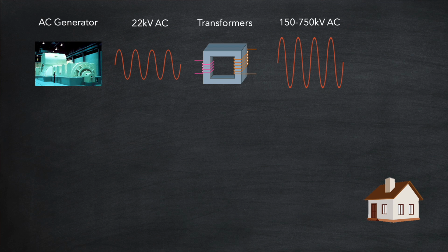They're just two sets of copper wire wound around a ferrite core. There are no moving parts. What's key is that there are a differing number of windings on each side. When stepping up, the left-hand side with fewer windings induces a much higher voltage in the right-hand side.